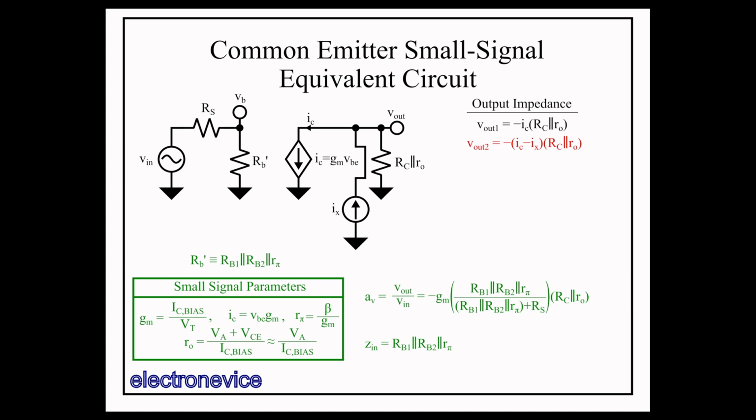In order to get the output impedance of a linear AC circuit, we just need to measure the change in voltage over the change in current when a current is drawn from the output. So we can use the voltage with the Ix load shut off as one data point, then use the voltage with our load current of Ix as the second data point to get the change in voltage over a change in current from 0 amps to Ix amps.